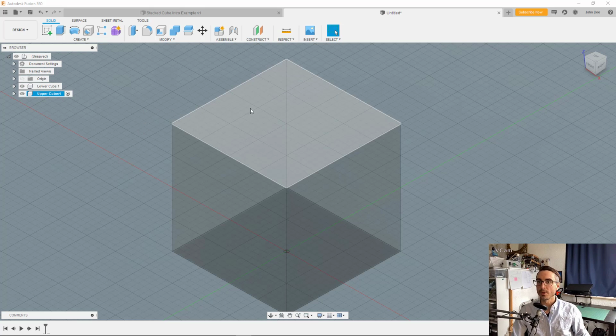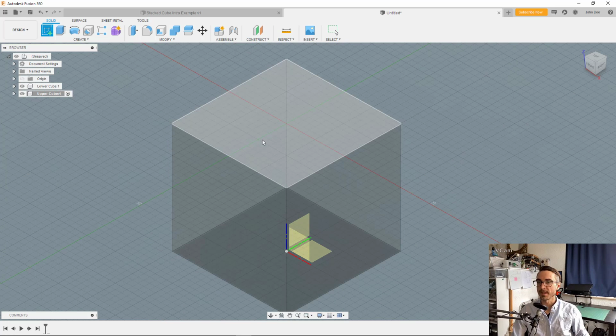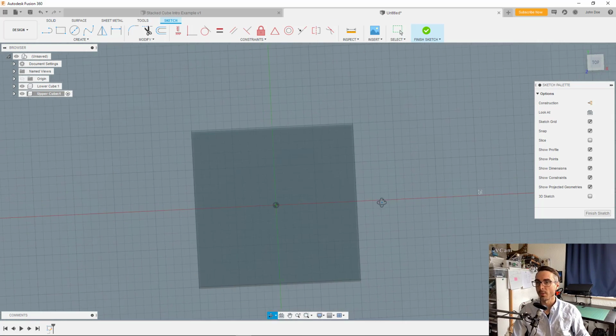We're going to create our three-dimensional object here very similar to how we created the big one by creating a sketch. Now that I've got more than just the origin, I've got some faces of this cube that I can select. We're going to put it up on top, so I'll click that and it snaps to the view right away to help us out.